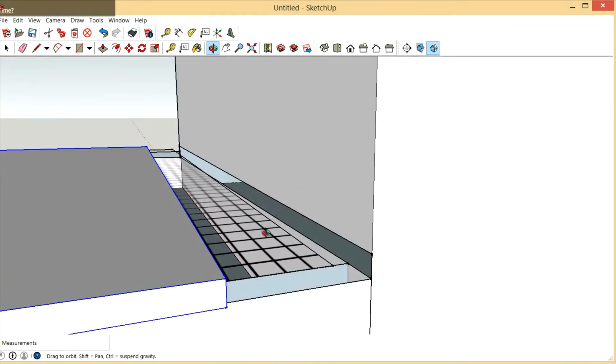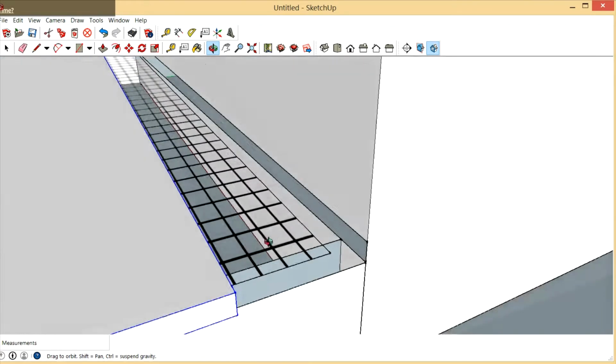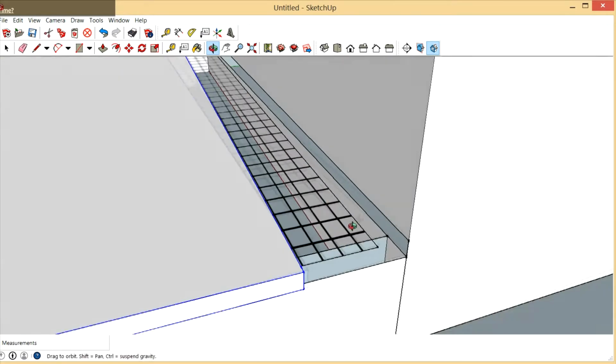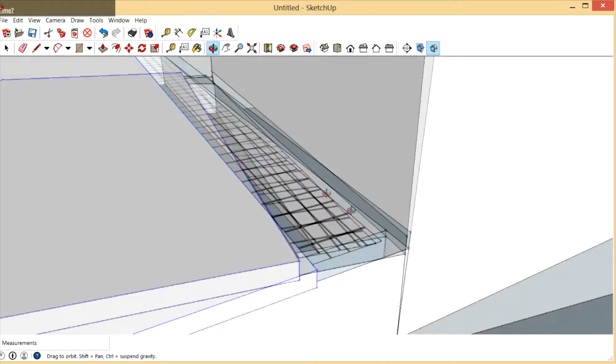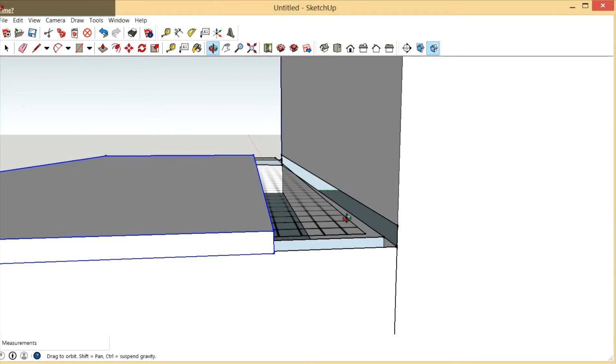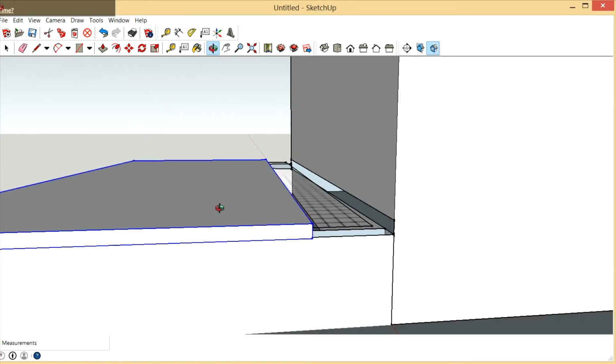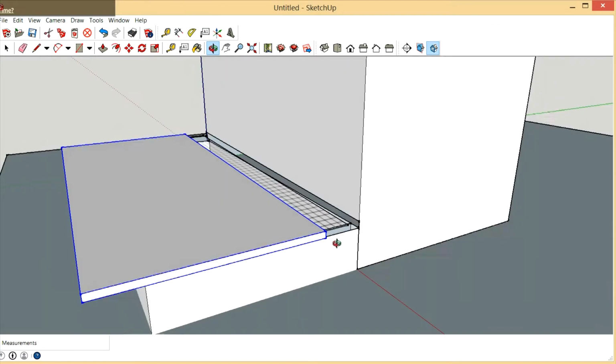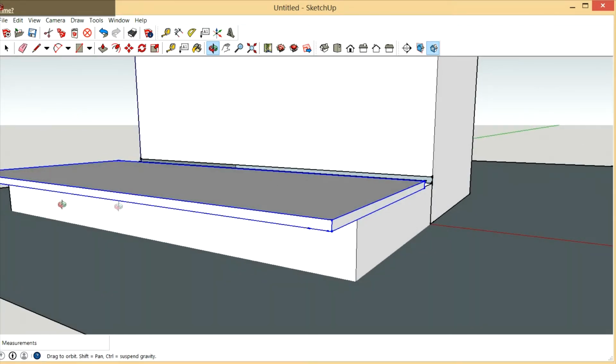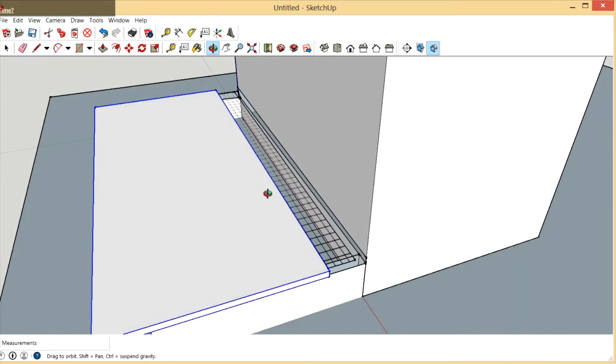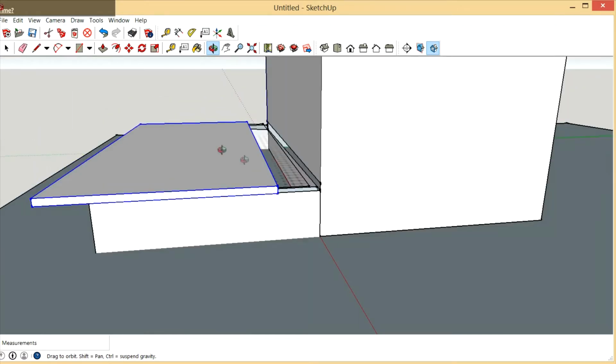One thing you can do, and I showed this in another video, I'm going to reference it. If you wanted to go through the trouble of building a ledge along this wall, you can put a pan to pour the concrete on, and that would be cheaper than filling up this whole thing with gravel. Oh, you know, it might be about the same, because you could probably get a load of gravel. Well, it depends on how big your porch is. For about $300, $325 around here, you can get a tandem load of gravel and fill this whole thing up, and then just pour the concrete on top of it.